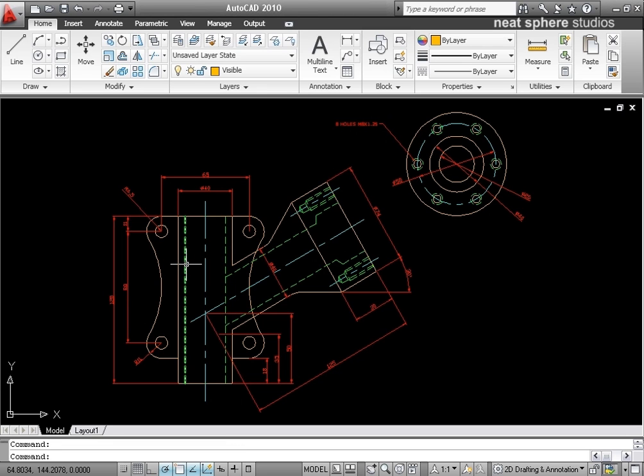Now, the advantage with this is that you can have large amounts of data within your drawing, but not actually have to have it visible at the time. So, if you're running a lesser computer, that can be good. If you've got a lot of detail like this, to me it just looks a little bit crowded. Obviously, this would be a manufacturing drawing, but still, it looks a little bit crowded to me. So we can always turn this detail off if we need to, or turn off hidden detail or center lines or things like that.